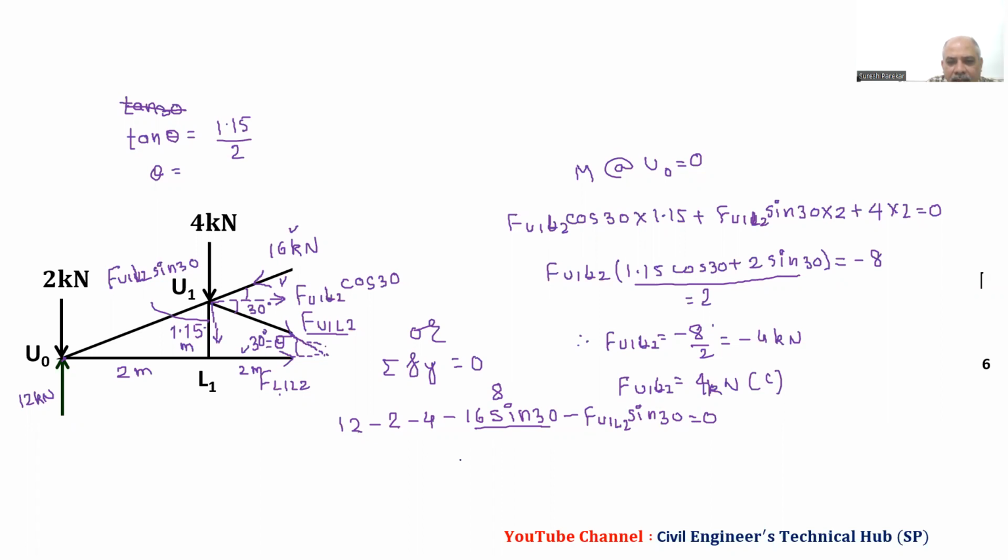So we have minus 2 on this side, and it goes to the other side and becomes plus 2. Therefore we get F U1 L2 equal to minus 2 upon sin 30, and this becomes minus. You can check it. You can take moment, you can take Fy equal to 0, or Fx equal to 0. You only have to check which one you can use that gives the value easily. And then you have to round up and show the correct direction.